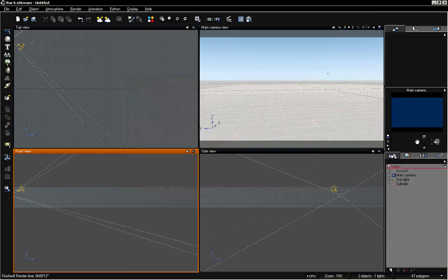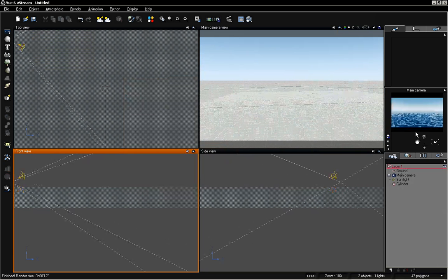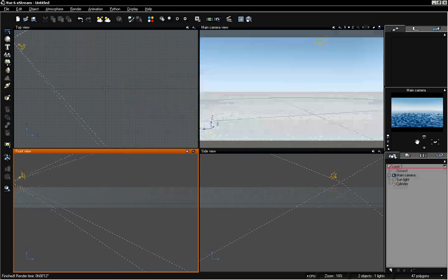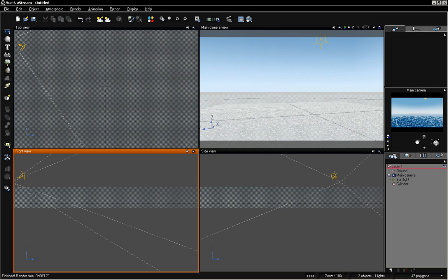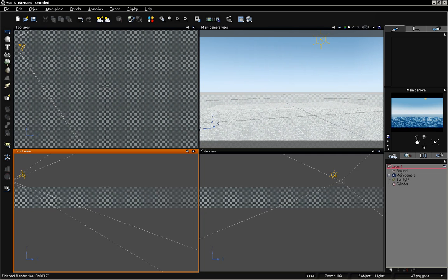So we're going to start building a scene, and then we can take a look at correcting some of these different errors, and also start adding in volumetric lighting and getting some light beams casting through our water to create some really neat looking effects, and also ways to keep down the grain, because normally with a lot of different volumetric light settings and ways that you would create those light beams, you end up with a very large amount of grain in the scene, even with some of the higher quality settings. So there are ways to reduce that, and we'll be taking a look at that as we start building the scene.